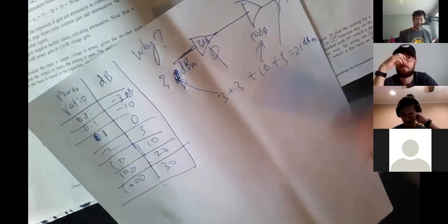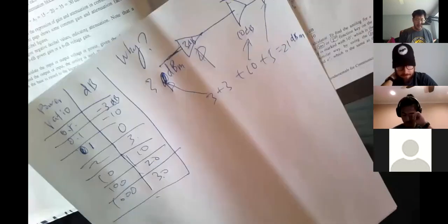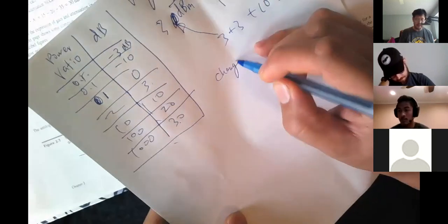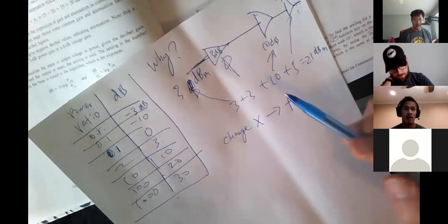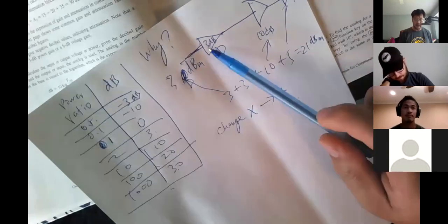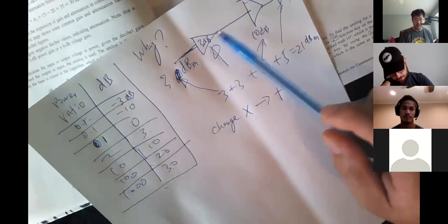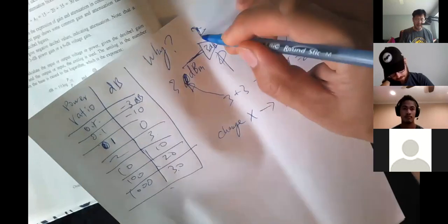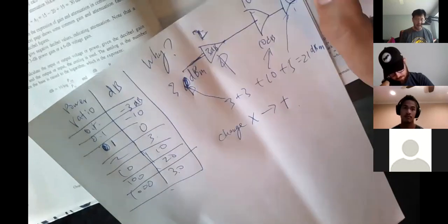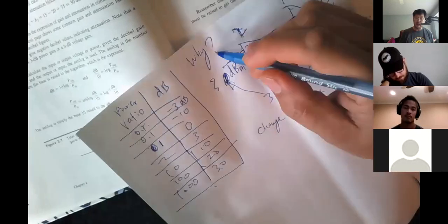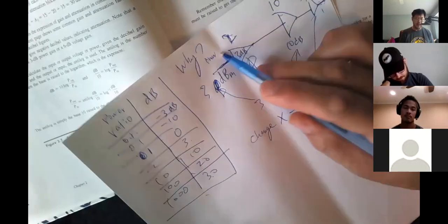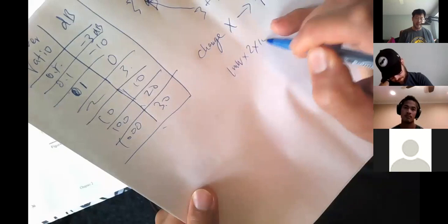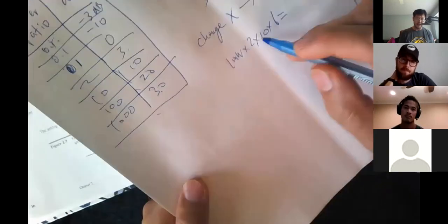Otherwise, you are doing multiplications. So basically, the decibels change multiplication into addition. Otherwise, if you have amplifiers in sequence, you multiply. For example, this gain is 2. This gain is 10. This gain is 6, for example. And the input signal is 1 milli. What is output? Without the decibel, you have to say 1 milliwatt multiply 2 multiply 10 multiply 6. That's what you do without the decibel. That's the ratio.